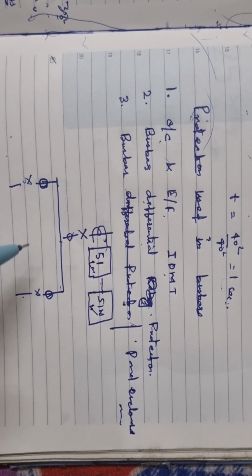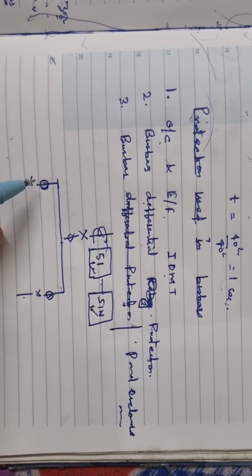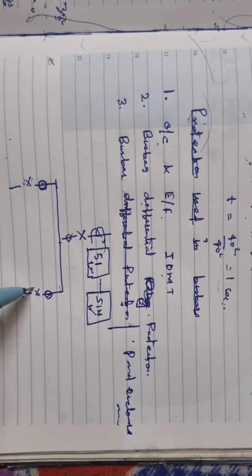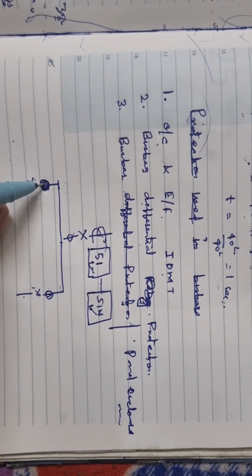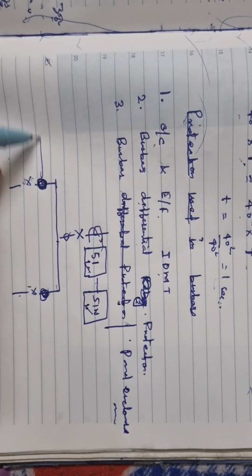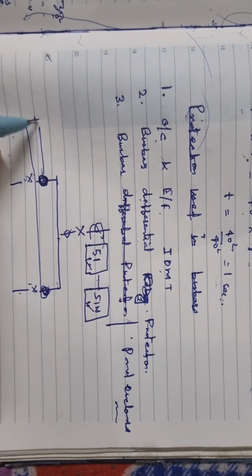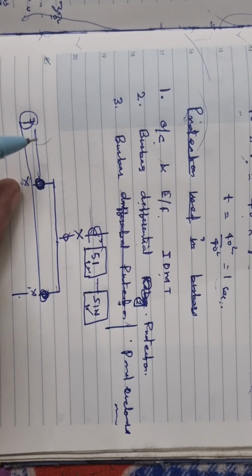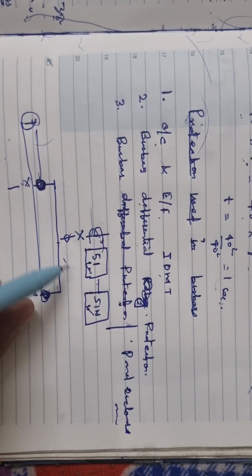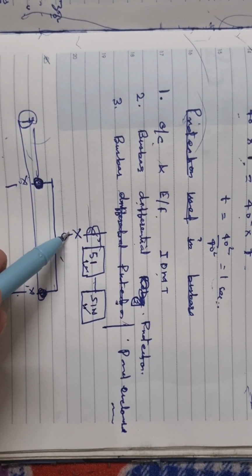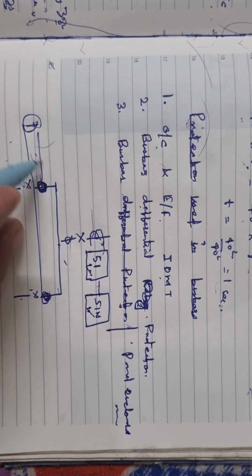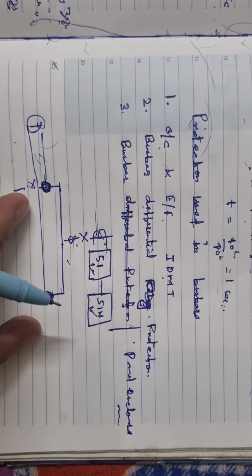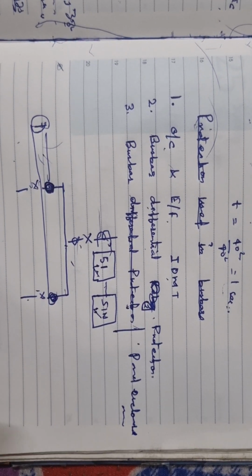What is happening now? The incoming current should be equal to the sum of the outgoing currents. So for the outgoing current, you will measure from one CT placed here and one CT placed here. You bring both CTs together, adding this and subtracting that. If the result is 0, it should not trip. If it is not, there is some problem in the system, and it will trip the incoming supplies or the outgoing supplies.